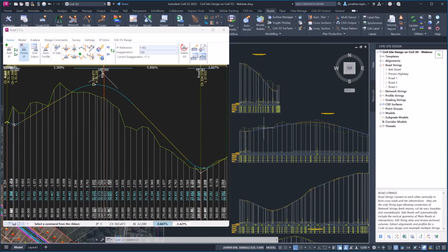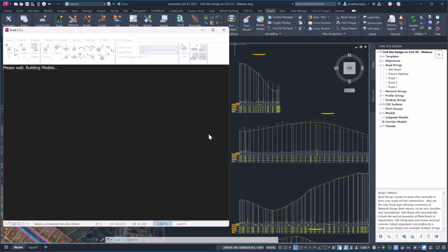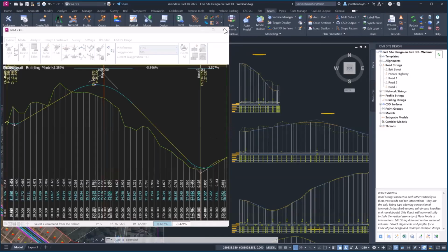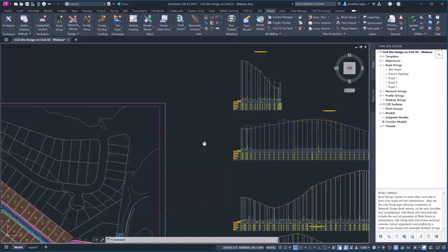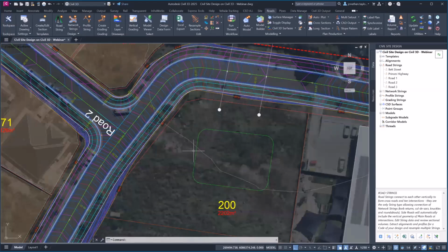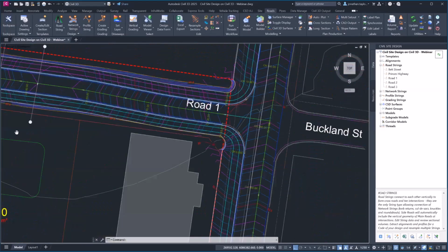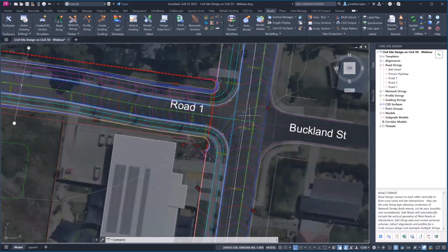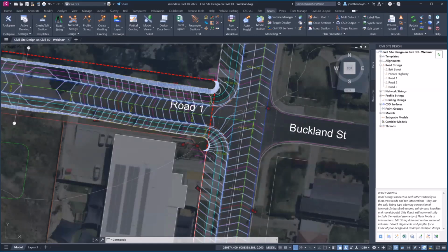Okay, so there is already the first connection with Civil 3D and showing you how those two things can connect together. One of the crucial things with Civil Site Design, as I've highlighted, is the fact that you can connect roads together and they will talk to each other, allowing you to form a connection, an intersection, and then curb returns. And again, just putting curb returns. This could be between an existing road. This could be between a rural road to a driveway.